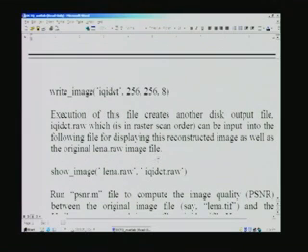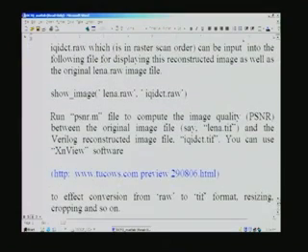What we need to do next is, we have got the reconstructed output as a file, and we succeeded in converting it into a raw file in raster scan order, and we need to show this so that we can visually see the picture and compare. For example, the original picture lena.raw and this reconstructed one can be compared visually, and then you can make out whether the picture quality is good or not. And in order to have some ready reckoner, you also have a computation called PSNR, the peak signal to noise ratio, and it is conducted over the entire image, between the reference image, that is the original image, and the reconstructed image.